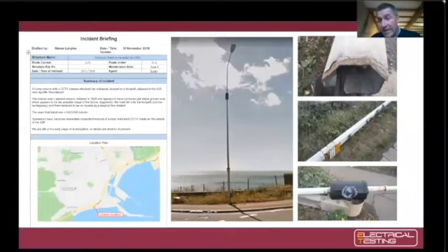You can clearly see on the right hand side there is corrosion at ground level, but the additional attachment has contributed to the column failing. The action on this incident briefing was that the immediate inspection and removal of all the redundant CCTV masts on that stretch of road. So the contractor responded to the safety alert.